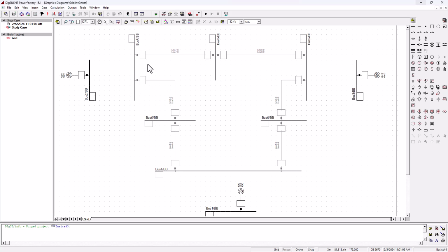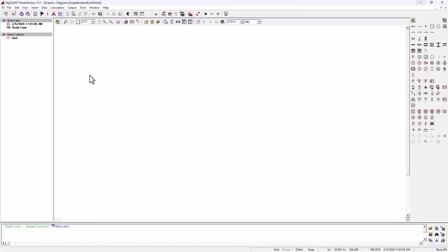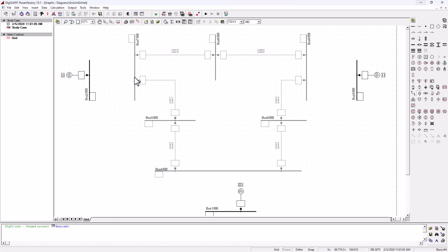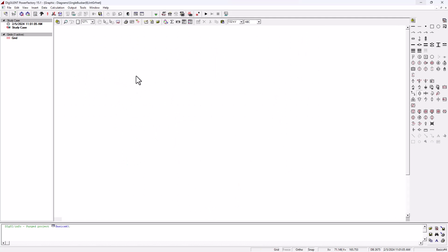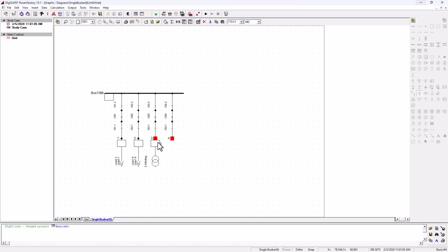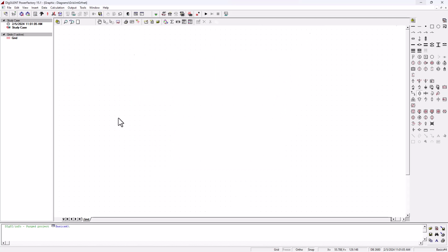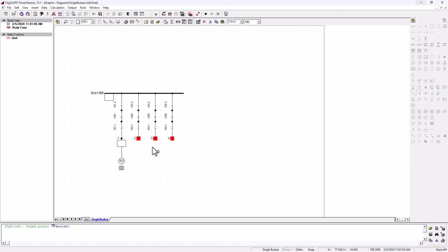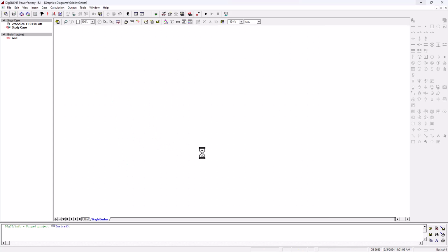So that is why we're going to take our transformers from these relatively low voltages to high transmission line voltages. To do that, I'm going to pick up my 2 winding transformers, and the first one I'm going to connect here. I've got plenty of cubicles here, cubicle 2, and I will connect it to bus bar 7, cubicle 3. Great. And I'm going to move to the next one on this bus bar, the slack bus. I'm going to find cubicle 2 here as well.